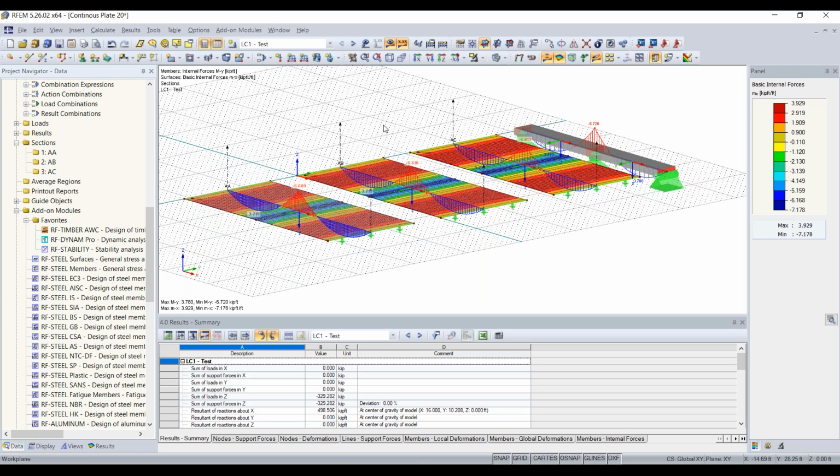Of course, you can draw a surface with the relevant materials and properties for a semi-rigid diaphragm, but it's not an actual diaphragm element in the program. It's really just a surface or a plate element, and we don't provide the analysis with chords and collectors and things like that at this point. So it's just purely FEA. Hopefully that answers that question too. I think that's it for now.